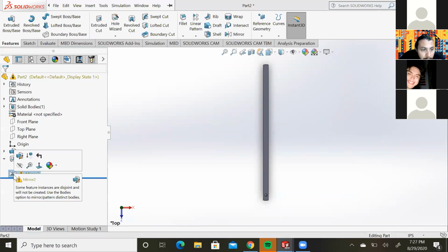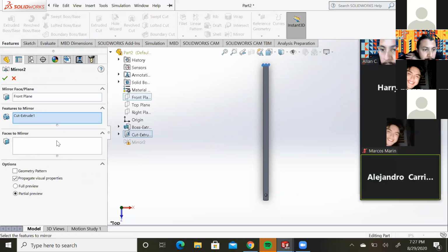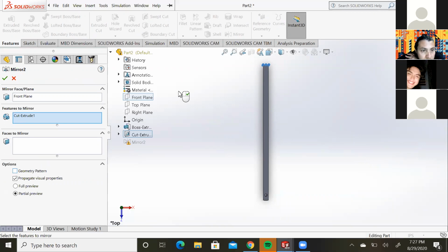Nope, same. Edit it. Go to the edit. Click on the front plane. Oh, that's why. Because you didn't extrude. Yeah, you didn't extrude mid plane. So basically, it's mirroring the feature, but not the part, basically nowhere. Because the front plane right there, what you see underlined in blue, that's basically the line of symmetry. Oh, okay. So it's using that as the half point. Yeah.